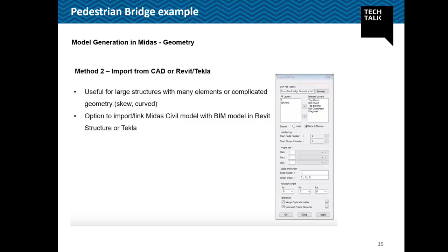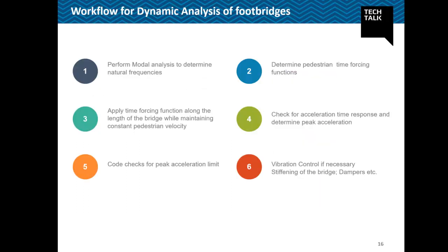So now we'll be going into the main part of the webinar: how to conduct dynamic analysis of the footbridge. First we will see the workflow of how to conduct a dynamic analysis. When we are conducting a dynamic analysis on a structure, the first step for any type of dynamic analysis is to perform a free vibration analysis